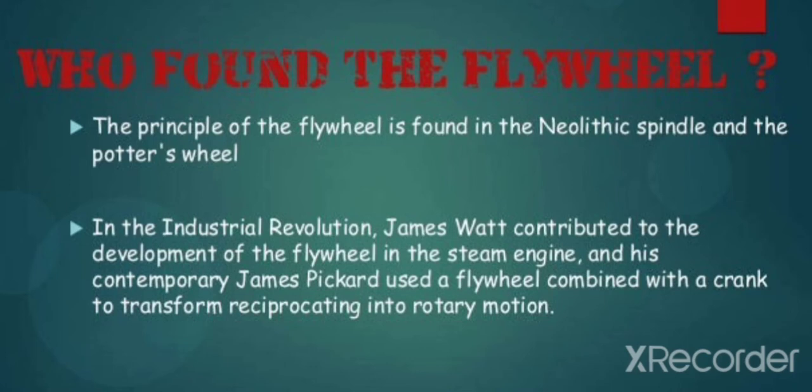Okay, actually governor is used to control the mean speed of engine, whereas flywheel is used to control fluctuations in energy. Okay, last, a flywheel is used to mitigate cyclic fluctuations in energy, but this governor is used to supply the fuel as per load. If load increases, engine speed decreases, and this governor increases the required amount of fuel so that engine speed can be maintained.